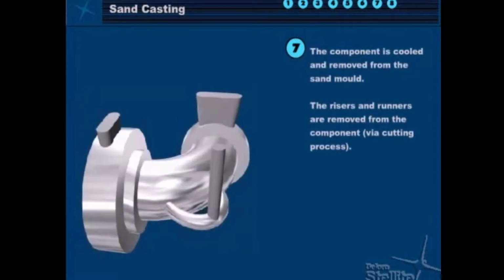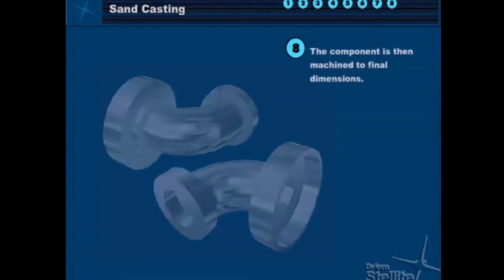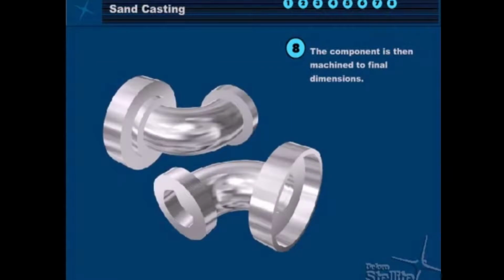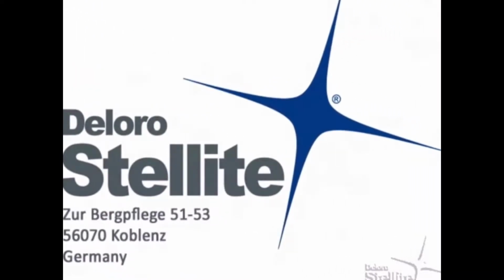Metal casters call this sequence finishing of as-cast surfaces. Note that the cutting off and blending of the process interface geometry, gates, and risers is done by hand. Some dimensional capability of the mold itself is coarsened. Finally, the machining and/or fabricating on a casting to reach final net shape is always small compared to other metal shaping processes. Castings are always mostly net shape as cast, sometimes 100%.